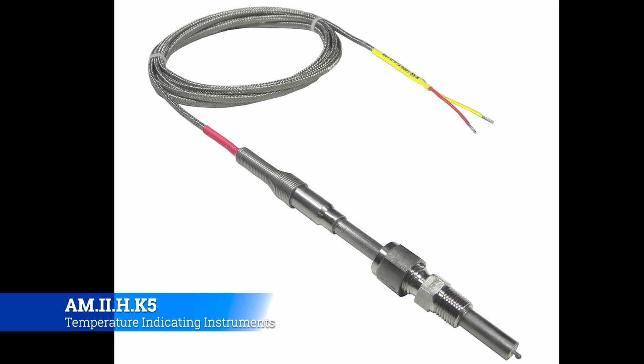But because they're a lot more complicated, and they're not so locked in physically like our bimetallic thermometer, you can have a lot of errors with it as well. And so you'll end up doing a lot of resistance checks on things like that to know, is there an internal resistance that has crept up because of degradation over time.